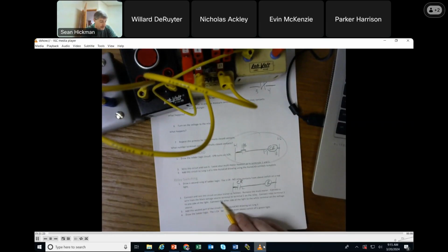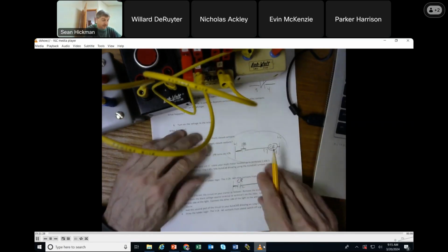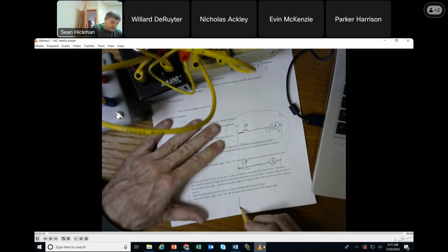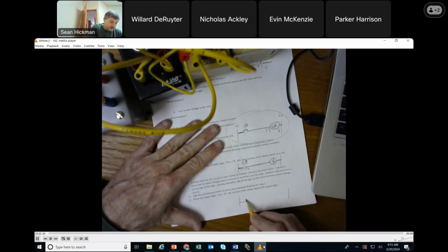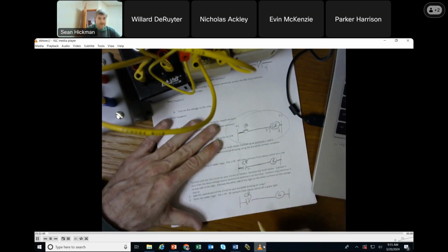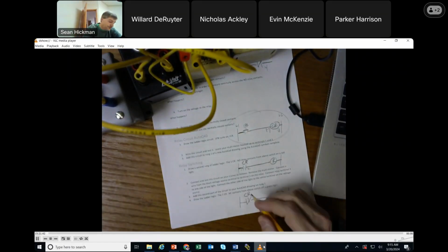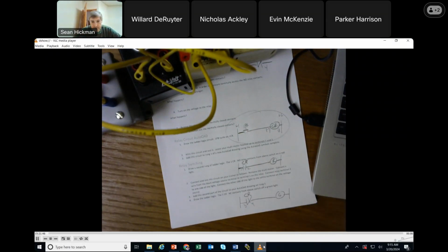So we did this, connect terminal 2, we did this, add a second one. I'm adding on to this. Normally closed turns on a green light. And this is still the CR closed, which is 3 and 4. 3 and 4 turns off a green light.